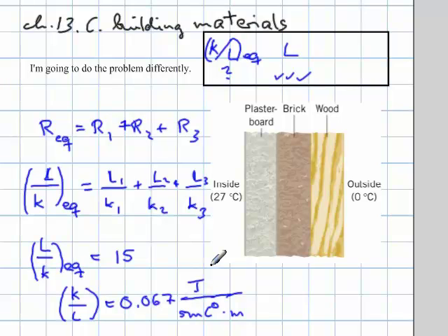By the way, that 15 that I calculated a moment ago, the reciprocal, which actually is the resistance, could be considered an R value. If you want to compare that to the real R value that you find in the store, well, you cannot use metric values here. You would have to get the joules into BTU, the meters into feet, and the Celsius degrees into Fahrenheit in order to compare that.